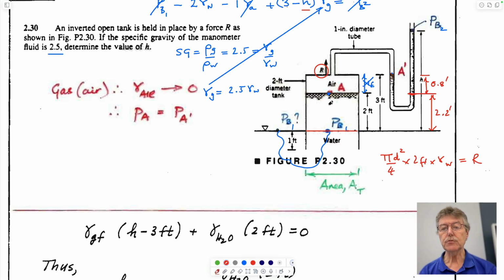So it's the weight of this water which you're picking up. It's cut off here because just like in the meniscus problem, you can cut it off at the bottom and lift it up. And therefore it's just the weight of this block of water that you have to worry about. Doesn't matter if it's a vacuum here, it's all self-contained. Of course there'd be a weight of the piping here, but that's negligible.